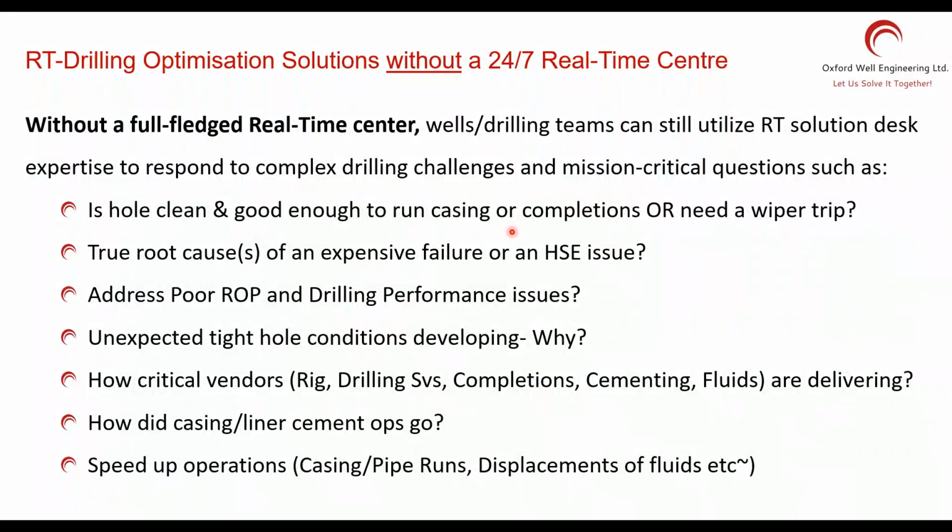If you are a small geothermal operator, I would suggest going with this option, not to have a real-time center. You can just have a desk for real-time center. You can train someone to run this desk. You can do everything that the real-time center does. It will not be 24/7. It will be only customized to suit difficult hole sections. For example, if you have a certain hole section or certain operation where you want real-time operation, analysis, and problem solving in real time, you may engage it, you may disengage it. You don't need 24/7 for the whole duration. It will be too costly for you.